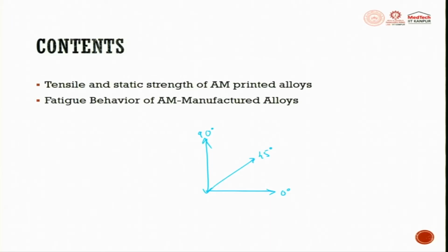But in additive manufacturing, since we are doing layer by layer, the biggest challenge is going to be across this direction and along this direction, and if you cut it in this direction, you will get completely different properties. And if you do it in metal and start with powder, you will have a different property than for the same thing done in bulk.